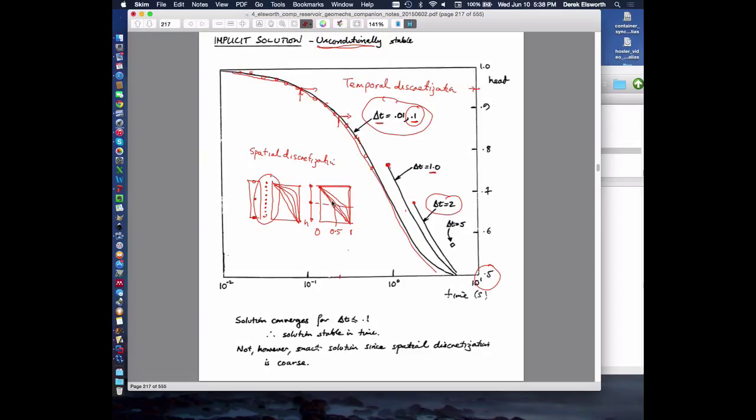And the other thing is discretization, and so you can compare that to the conditionally stable one, which just oscillates and goes out of control. So those are two different behaviors. But don't, because it reaches some reasonable value close to the steady state, assume that necessarily it's right. It's not necessarily right because, one, the time discretization might not be fine enough. And certainly for the one we just did, at 1,000 seconds, it would be off this map, over here somewhere. It was roughly 0.5. And so that would kind of be true, but we've missed out all the earlier stuff.